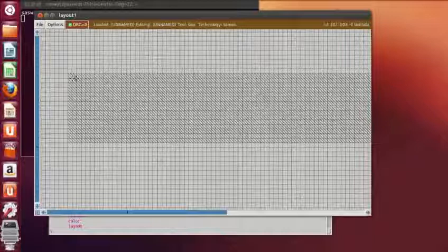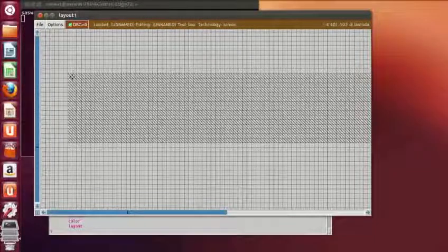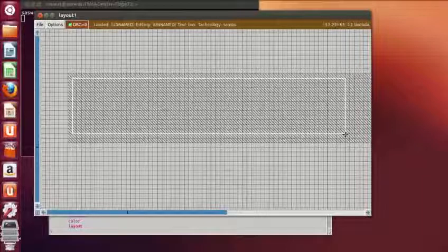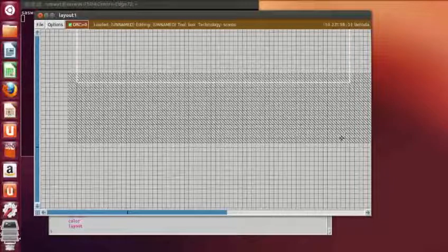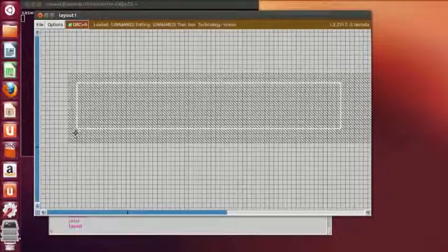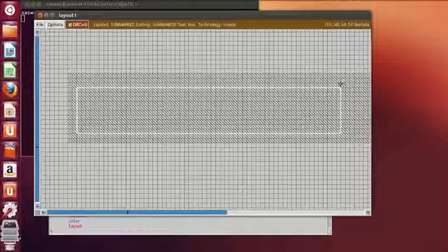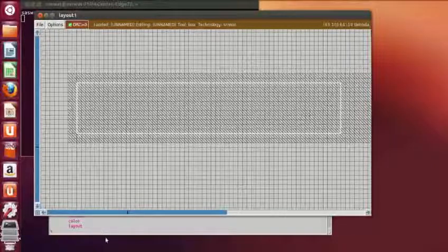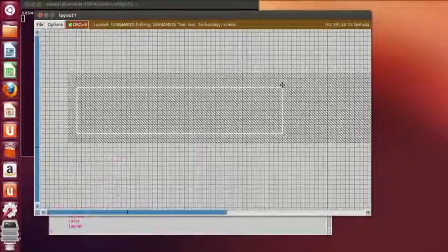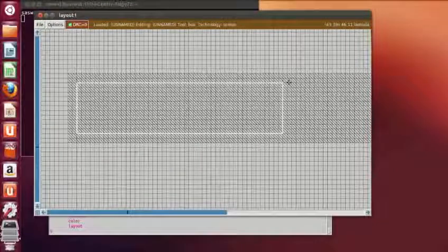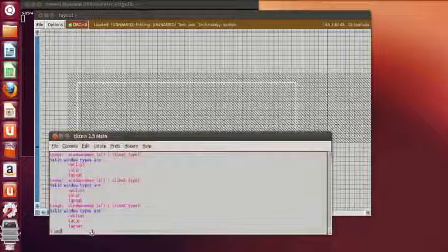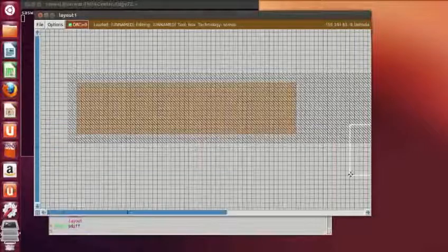the two PMOS, that is the first and the second PMOS, have a common drain. So we can draw like this for two at a time, or we can even reduce this area up to this much, and then type paint pdiff, that is the p diffusion layer.